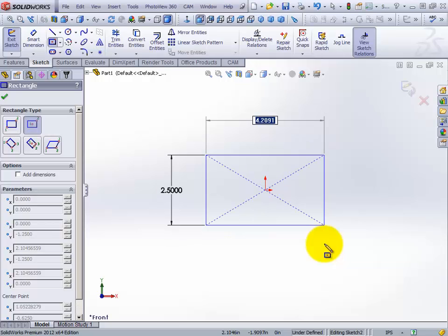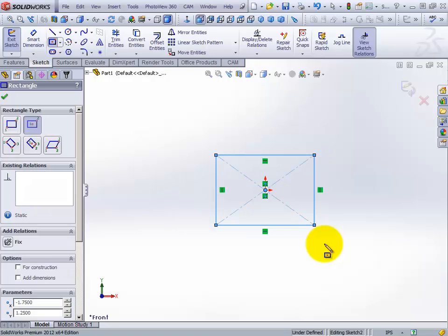Now look what happened. The top box is saying, okay, how wide do you want this box? Well, I'm going to make it 3.500, enter. So I have just made a box, and I've already got some numbers on it. But you notice my rectangle wants to keep drawing. And I don't want to do any more drawing in rectangles, so I'm going to show you a trick.